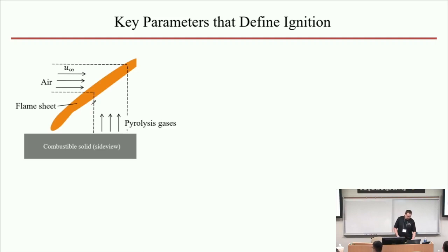So I'm going to take this control volume that is highlighted by this dashed line right here of the flame sheet, and I'm going to note that when the stable flame exists, the heat production inside this flame sheet divided by the area projected to the surface can be defined by the following expression, where the mass fluxes are of individual gases, delta H are the heats of combustion of individual gases, and when you sum them up, you end up with the total heat release rate in this control volume.